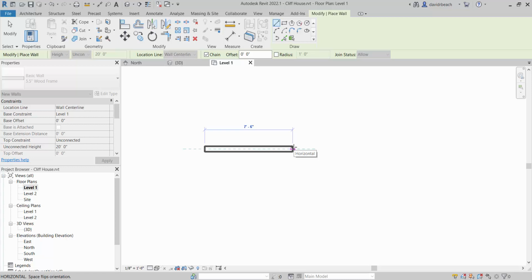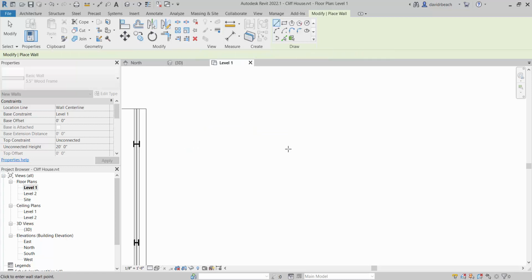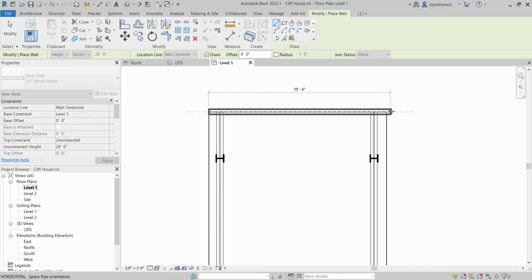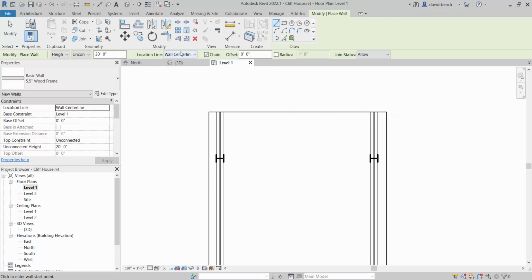But when I'm drawing something, if I'm working on interior walls, something like that, I might want to draw by center line. Okay, but I find myself doing this more times than not. I have something kind of sketched out for where my building needs to sit. And if I'm drawing this with a center line, you can see rather than going to the outside edge of that platform, it's drawing center line. So I rarely use that center line as my location for drawing.